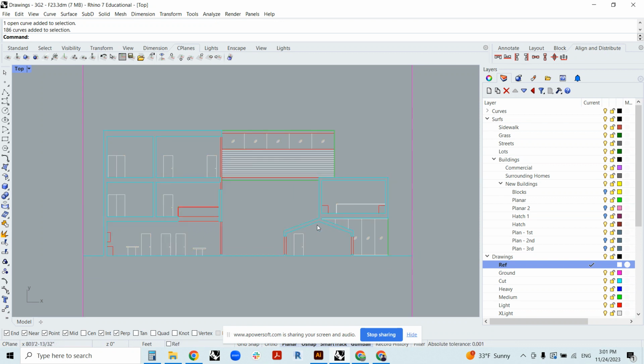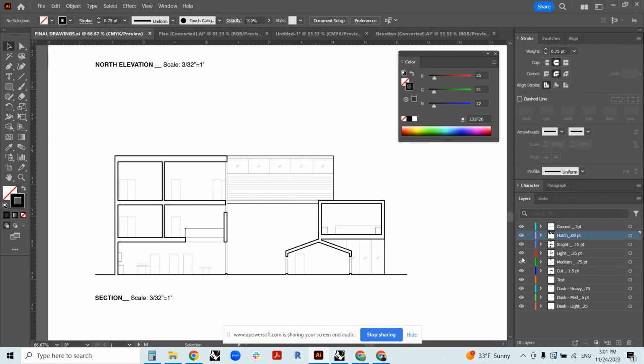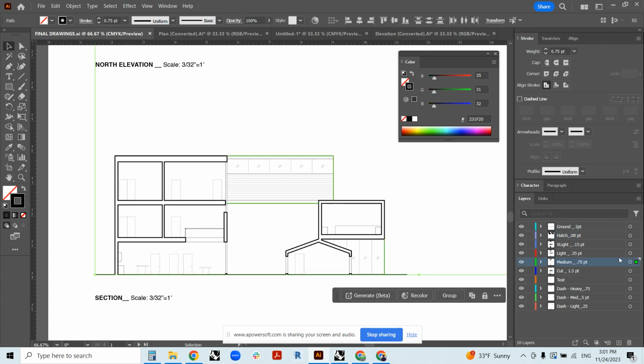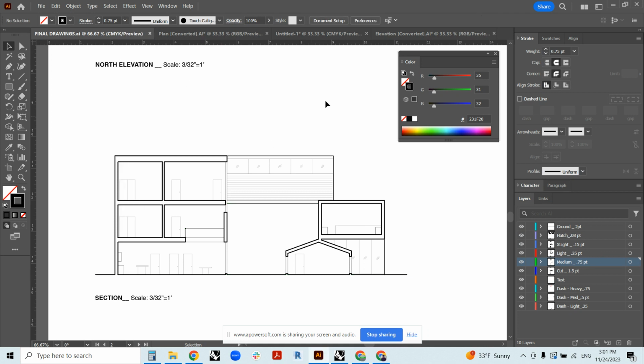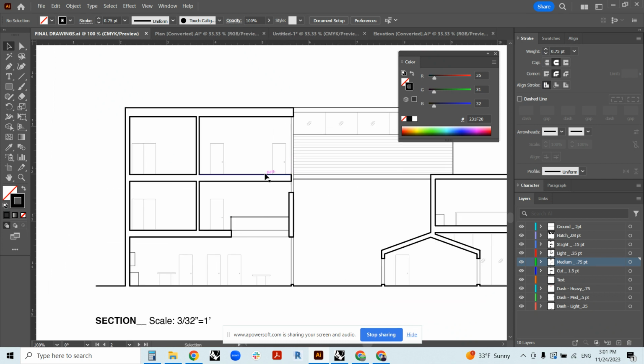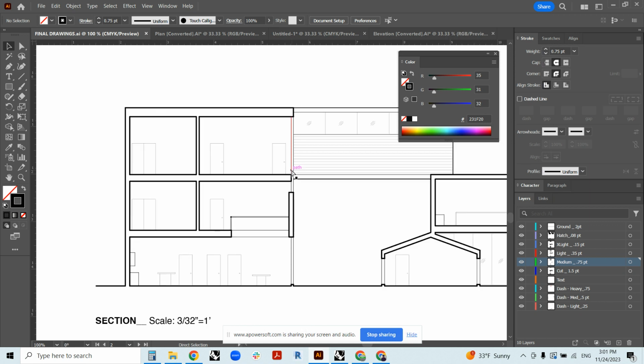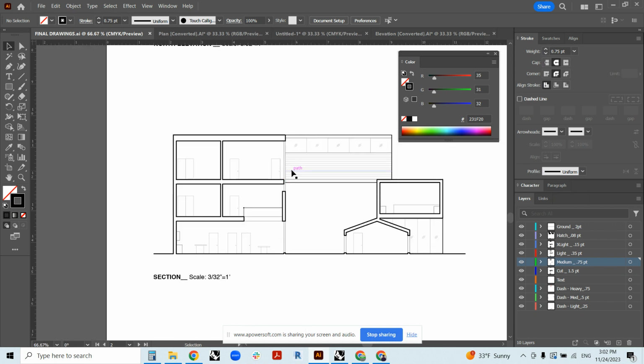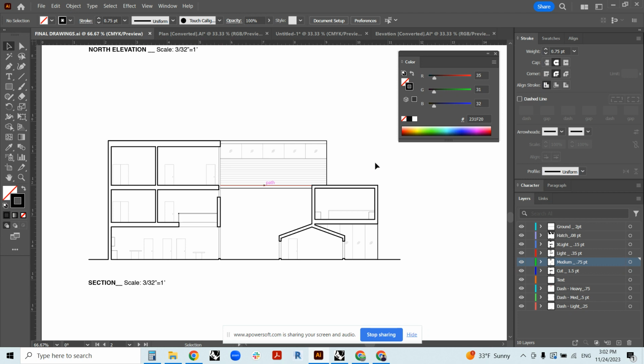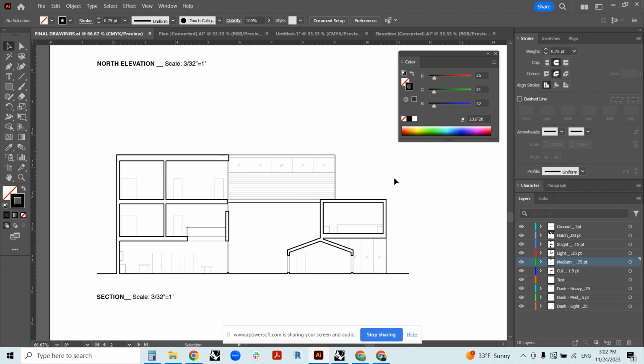Same thing: select, export at the proper scale, and then open it in. And again, a little bit of layer management, getting everything on one layer, but then in the end, you can just select everything again, 0.75, and then everything is synced up. So you'll see, again, a high level of distinction between the cut line and the background information that'll really allow your drawings to read as spatial. So again, follow these guidelines, and I think it'll set you up well.